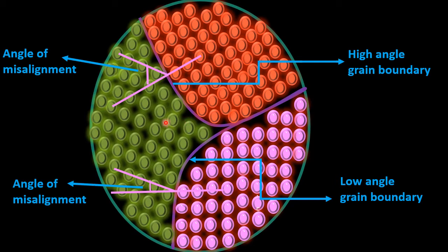So here we need to discuss one thing more about these grain boundaries: the atoms along these grain boundaries in polycrystalline materials are chemically more reactive as compared to the grain itself. This is just because of their grain energy. So the impurity atoms preferentially segregate themselves along these grain boundaries because of the grain boundary energy.